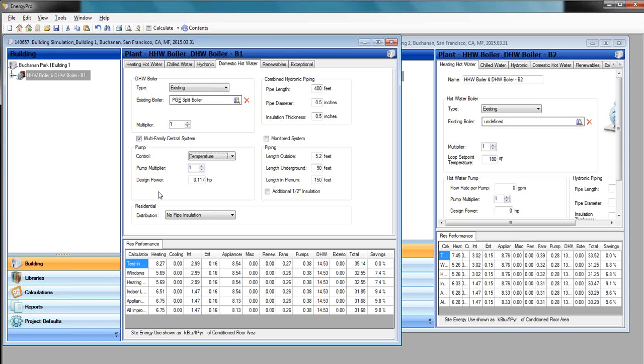It can run up to a half horsepower, and that's not really how that pump is going to function all the time. So what is called in the industry a brake horsepower, you want to make sure you can find. Brake horsepowers are typically listed in the manufacturer cut sheets. So it'll be a rated horsepower and then a brake horsepower.